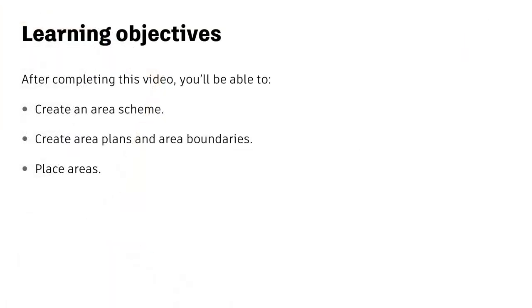In this video, we'll see how to create a new area scheme for a project. We'll show how to create area plans that relate to the area scheme and place area boundaries. And we'll also see how to place areas in the model.